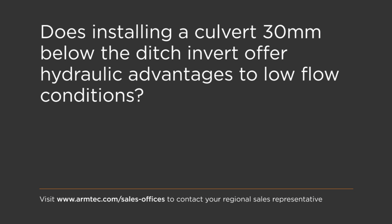Here's one. I've read that installing the culvert approximately 30 millimeters below the ditch invert offers hydraulic advantages to low flow conditions. Can you comment on that? It really depends on whether it's an inlet or outlet control culvert. It's kind of a difficult question to answer. But generally, what will happen is you install a culvert below the natural stream grade, and there's sediment in the stream, then it will accumulate in the bottom of the culvert up to that level. It's just sediment will follow the path of least resistance.